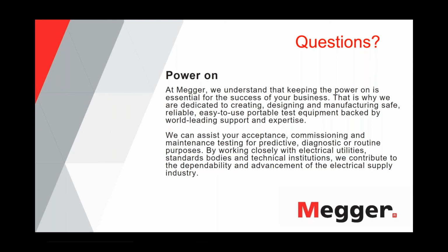Robert, what is the interval to conduct the VLF, tan delta and PD testing for an aged cable? Okay, so there is no fixed interval for this. And as Henning pointed out, this has very much to do with where you are on the life curve, the bathtub curve, because a cable is an asset like a transformer or anything else. So you can say it has a life curve.